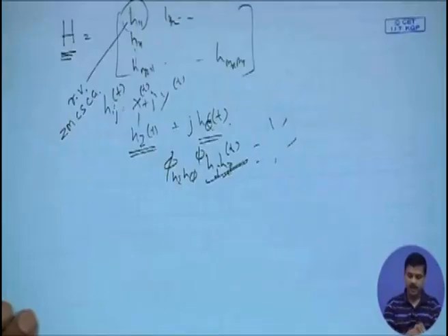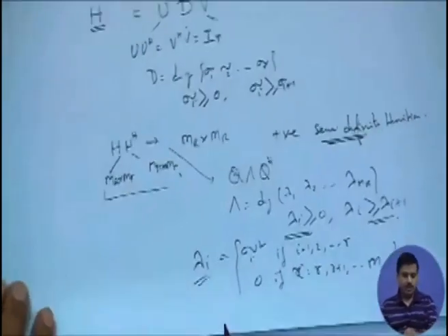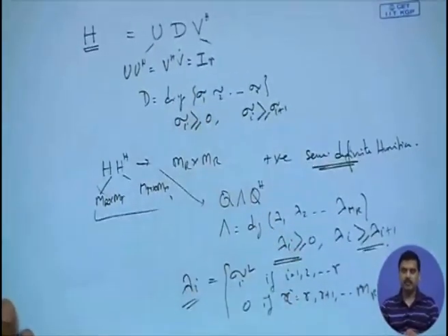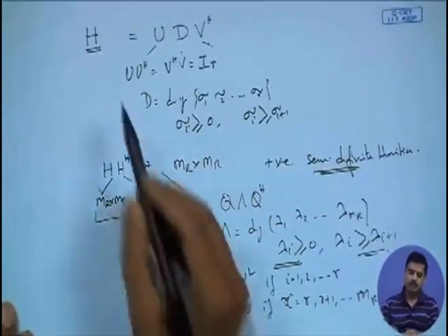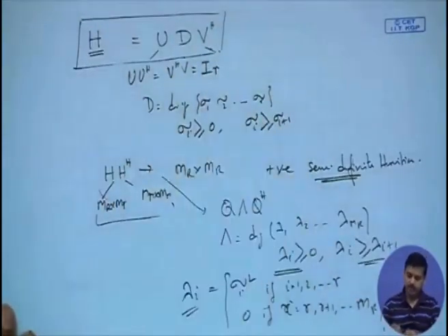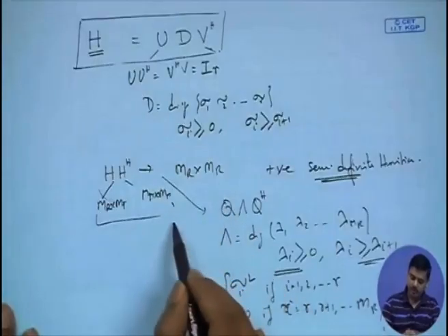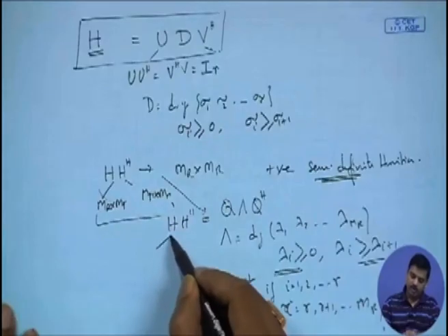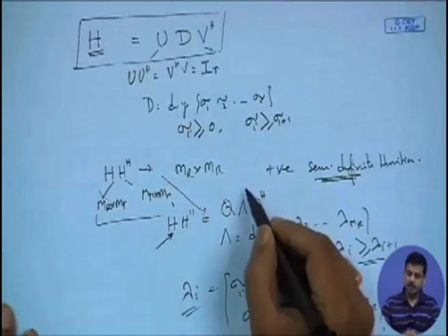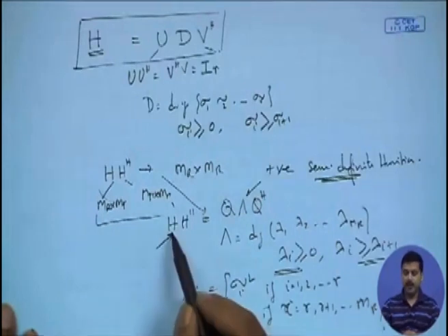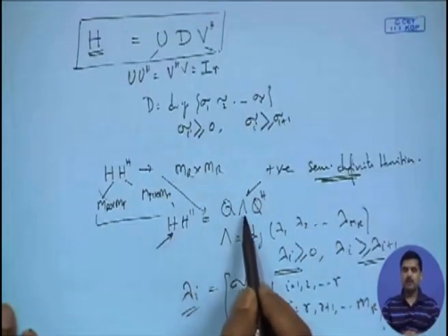So if H is random, what we have seen before, these lambda i's, these eigenvalues or the singular values, must also be random, because whenever we look at this expression, H Hermitian H can be factored into this, the moment H is different, of course it's going to have a different set of eigenvalues, and every realization of H will give us a different realization of the matrix lambda.